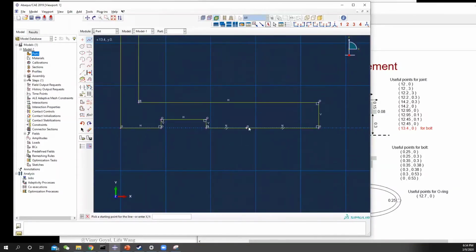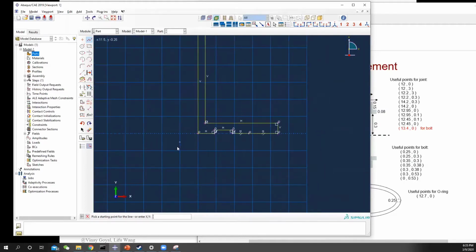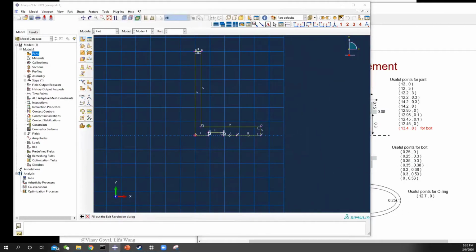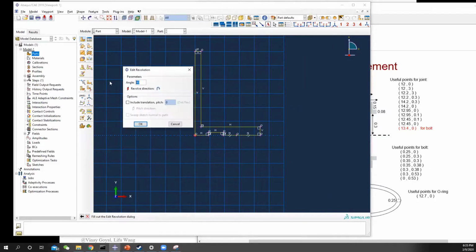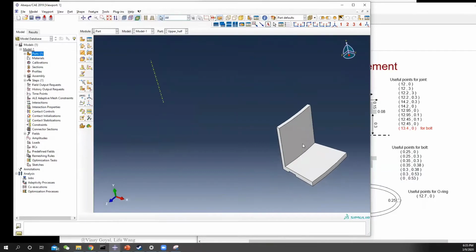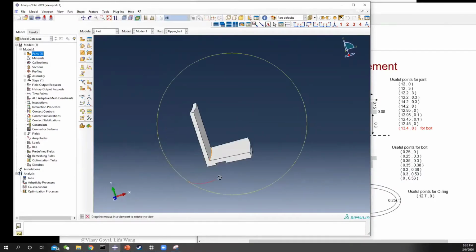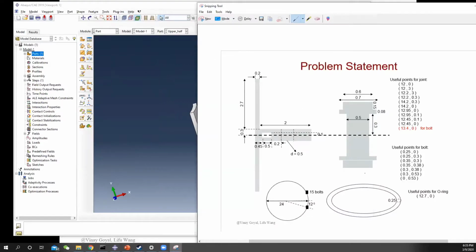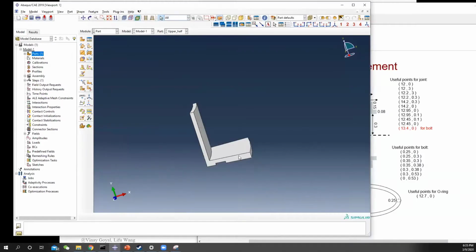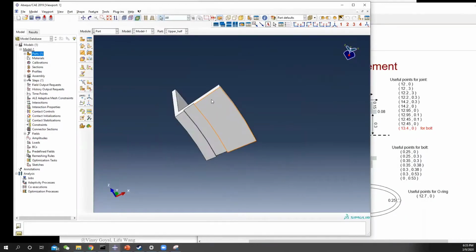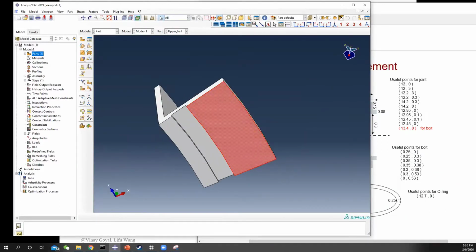Notice that you can also draw this point on the top surface. This is for cutting the hole later. Finish, then click done. This angle should be 12 degrees. You will have the geometry like this, but it doesn't have the bolt hole here. The bolt hole has diameter 0.5, so we're going to draw a semicircle and do the cut extrude here.